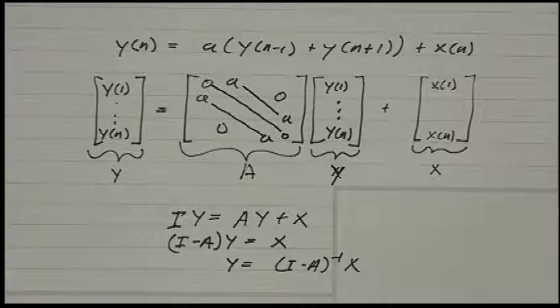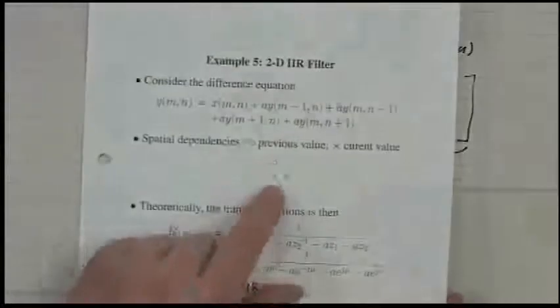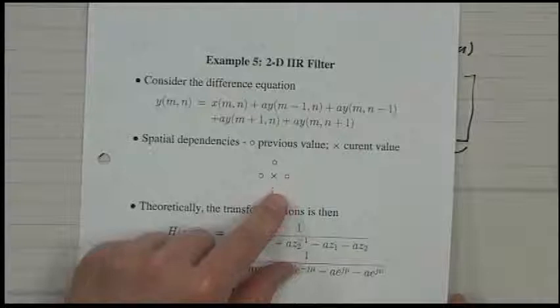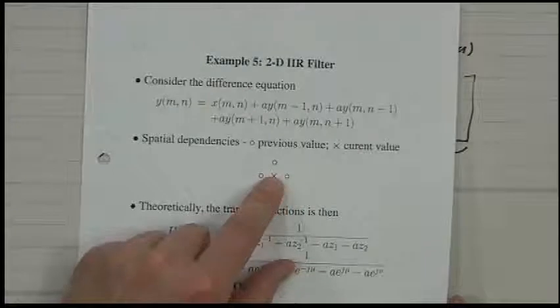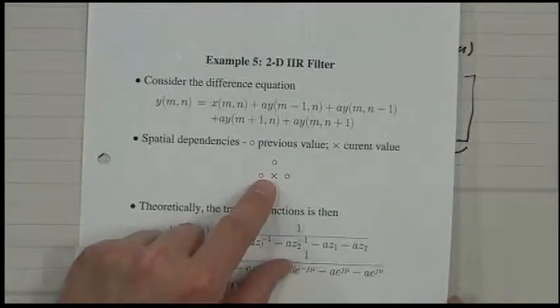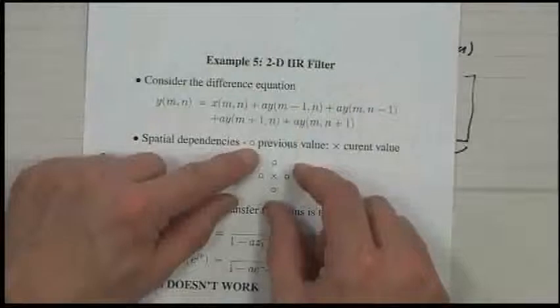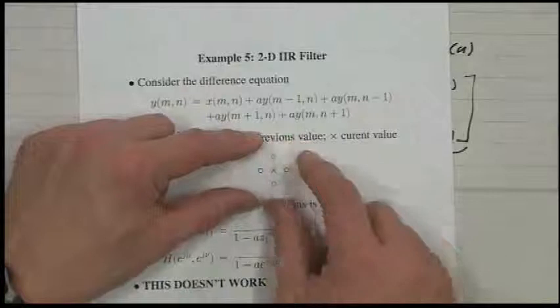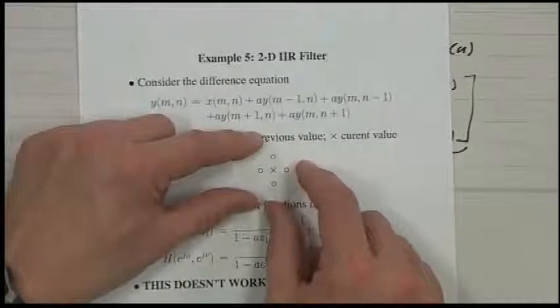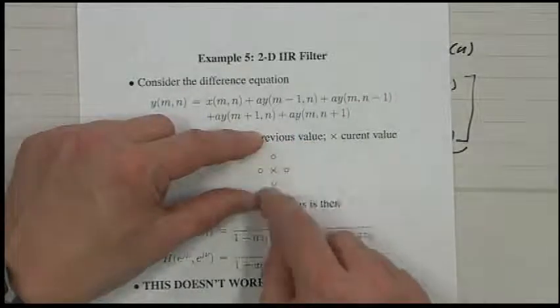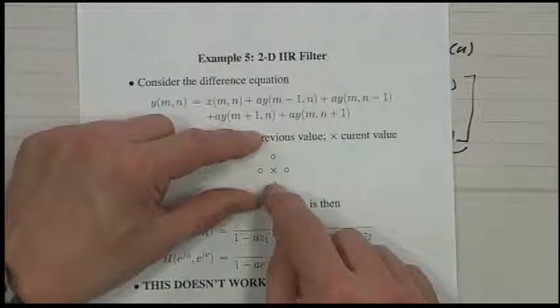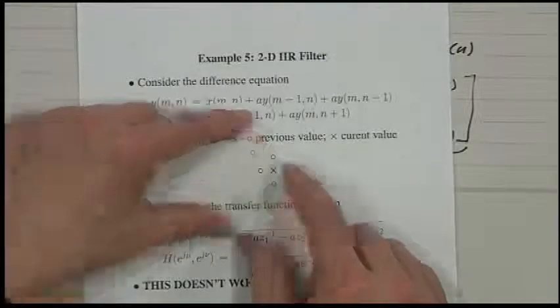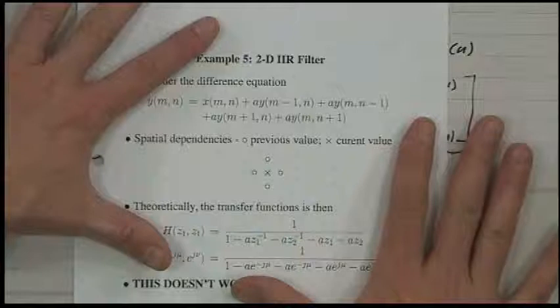As a matter of fact, this topic actually becomes important because there are important benefits to this model. The parameterization here is low, and it gets rid of the problem with anisotropy. So this could be used to make a filter which is much more isotropic. You only need 1, 2, 3, 4 parameters to implement it, as opposed to an FIR filter where you'd have a huge number of parameters.